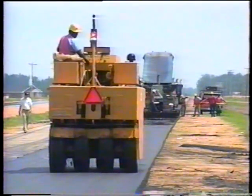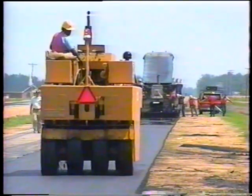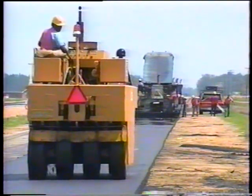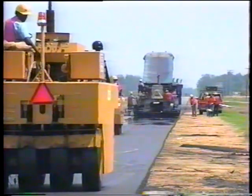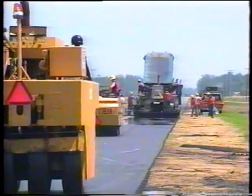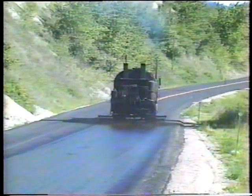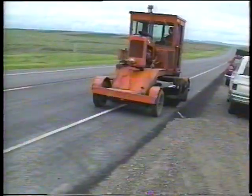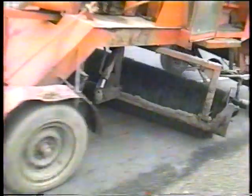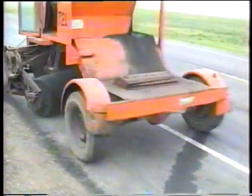First, get familiar with the equipment that will be used. The paving train consists of haul trucks, a paver, and 2 or more rollers. A distributor applies the tack coat to bond the pavement to the underlying surface. A power broom sweeps off the surface ahead of the tack application.